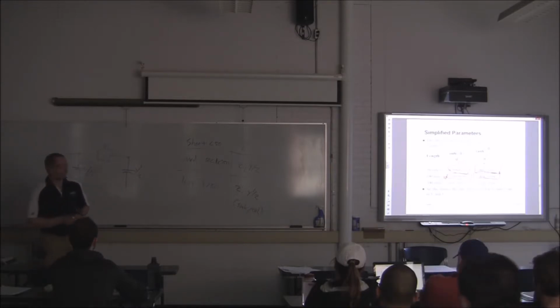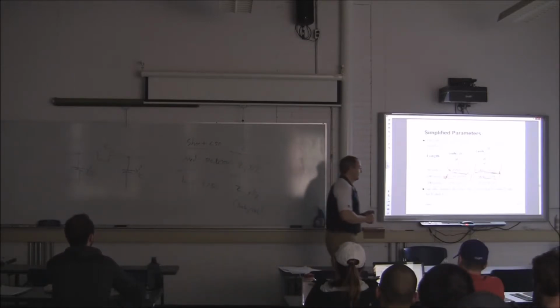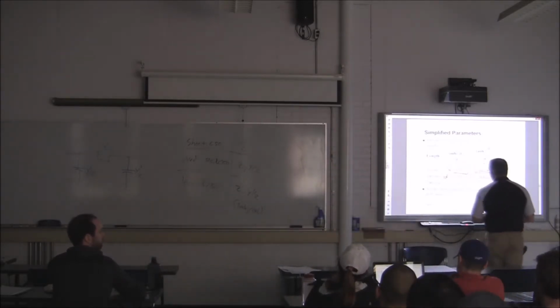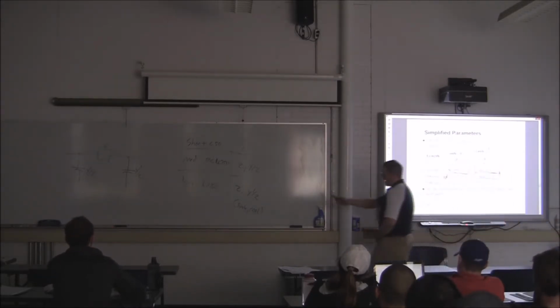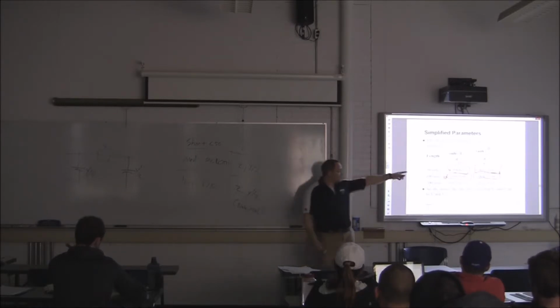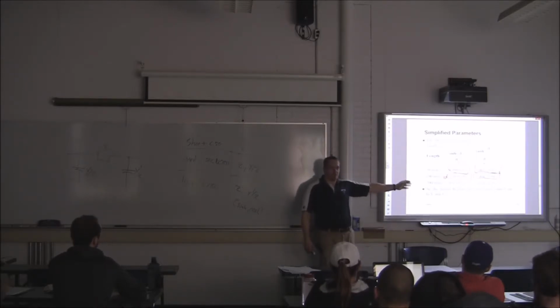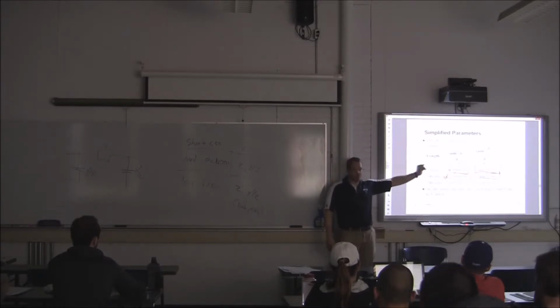That's how you analyze transmission lines of varying lengths. And here's the key. If you have a short line and you want to use hyperbolic sines and cosines, it's still right. It's actually more accurate, isn't it? Because you can see it still does a slight magnitude and phase shift. So you can always, always, always use the exact equations for any length of line. Always. If you have a short line, you can simplify it just by using z. Makes your work a lot easier.